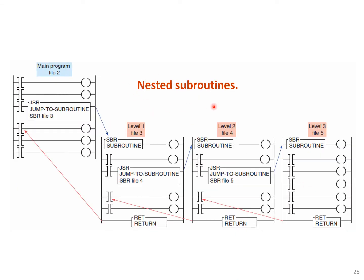Nested subroutines are possible. Here we have one example. We are jumping, for example, from this main program to file 3 and return to the main program. Inside the first subroutine, we could have a nested one, jump to file 4, and when it reaches the return, it returns to this first subroutine. And again, another nested one. So we have basically 2 nested subroutines inside the first subroutine.